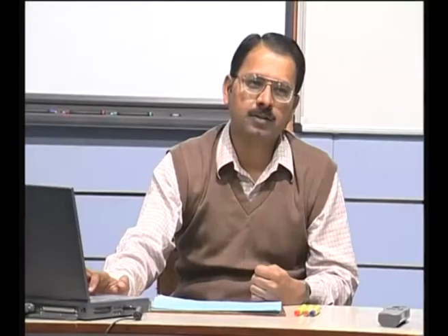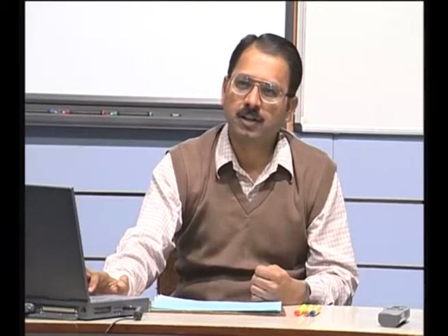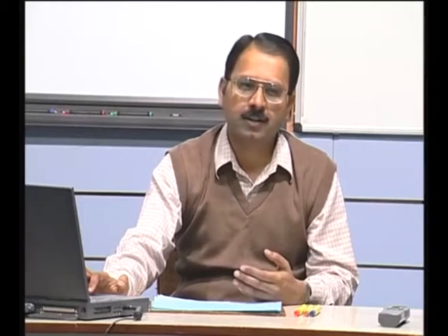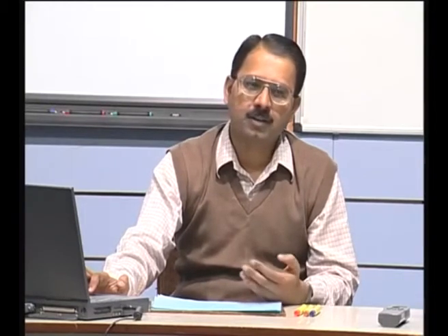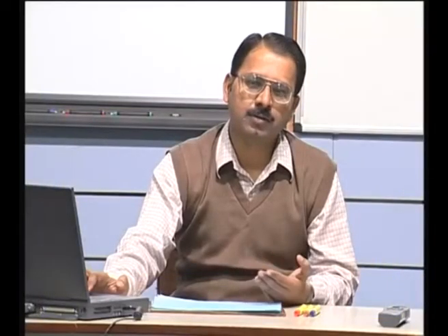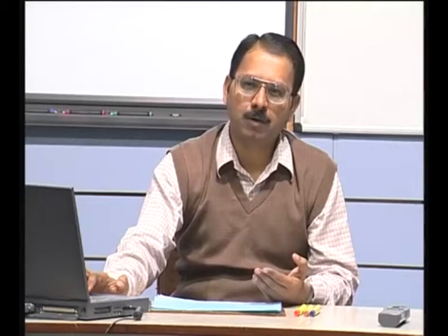For example, you may have heard of stereolithography, selective laser sintering, laminated object manufacturing, or fused deposition modeling. These are all examples of rapid prototyping machines which build an object slice by slice, and they usually use raw materials which are either polymeric monomers, or polymer or metallic powders to carry out the sintering process.